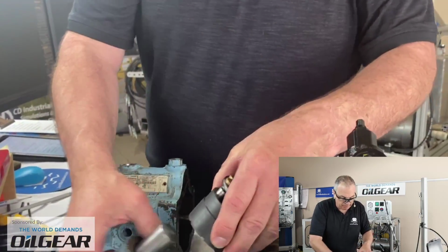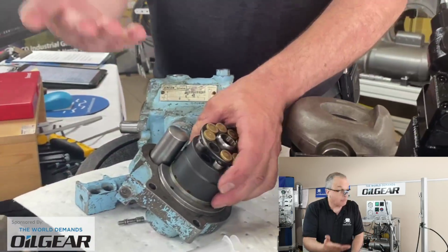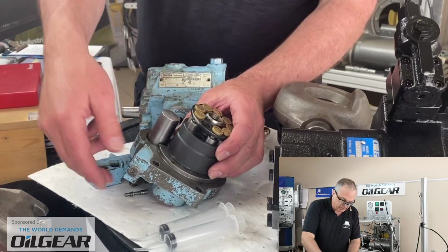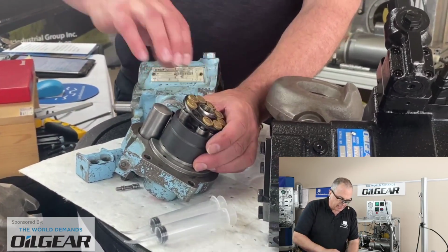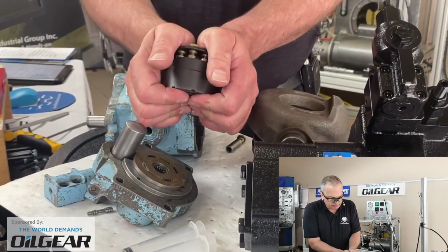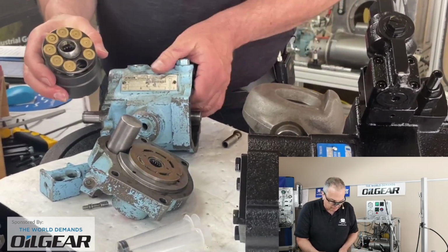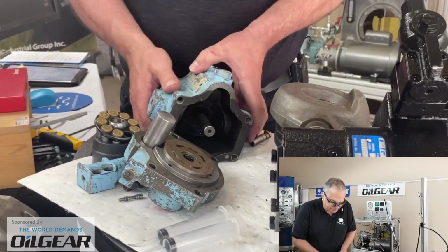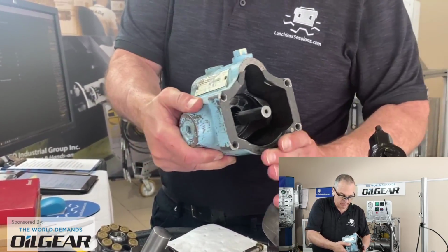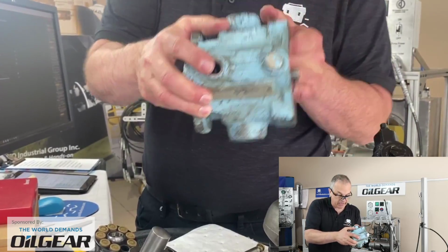As you put the pump back together, assuming you're a pump rebuild person, when you tighten up those cap screws to fasten the cap end of the pump to the body, you find in the last few threads there's some resistance. You're tensioning the slipper pads, the piston shoes, against the swash plate that you can see inside the pump casing. You see it in there at an angle. Looking in through the case drain, I can see the bias spring in there.